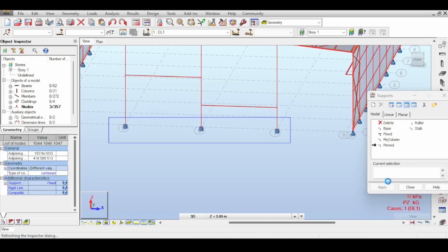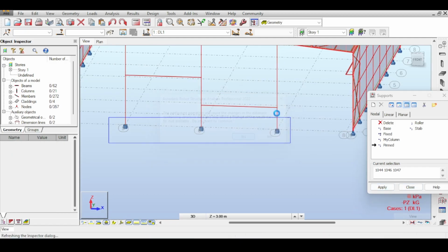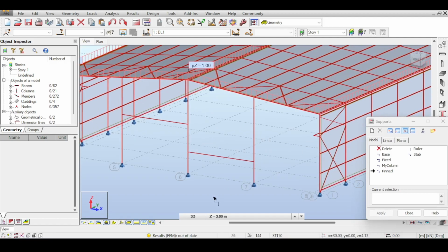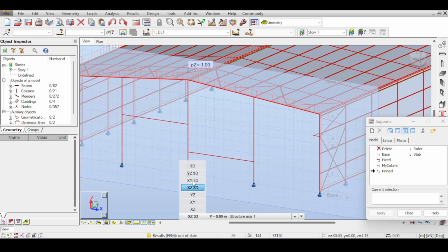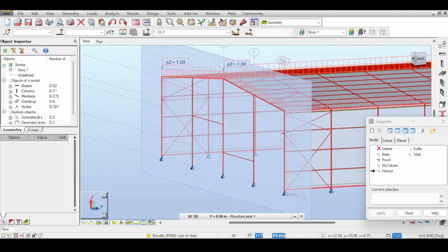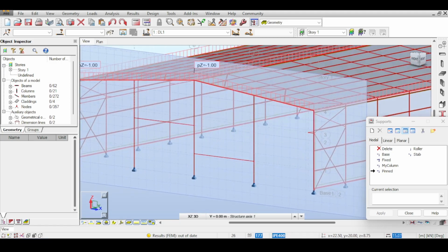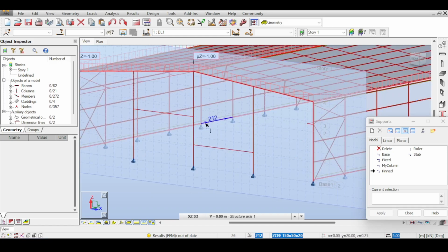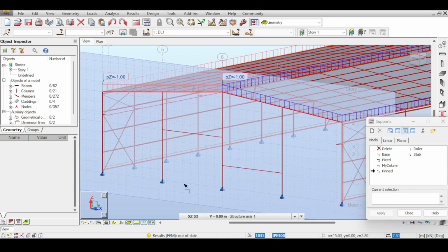The problems I have with stabilization, why am I thinking so hard? I'm thinking so hard because you have to stabilize in three major planes. You have to stabilize in the XZ plane, which is this plane, and the stabilization in this plane is easy. It's stable because you have frame action here. The frame action here stabilizes the frame, or you can even put some bracings here and then everything is fine. That's one thing. This plane is easy to stabilize, but this is not the only plane.